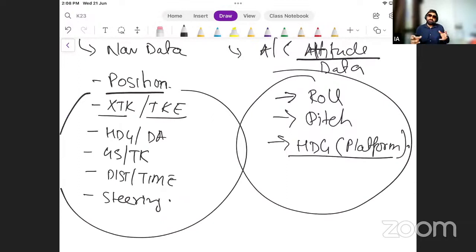And then we'll have computers that will feed the data and convert the data into the requisite information that we need. And then through the control and display unit, we'll be able to select what function we want to check, feed in the data and check information. Then, of course, the navigation display of the aircraft will give you related information. So this is how you directly get true heading, true directions of the instrument, and you cannot totally depend upon your magnetic compass or remote reading compass or other compasses, because when your aircraft has INS, you are getting adequate information.